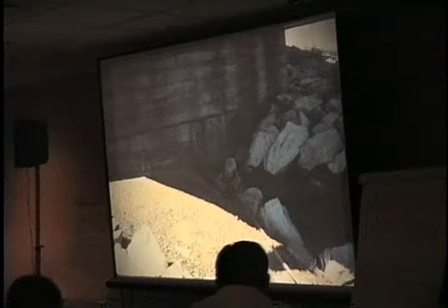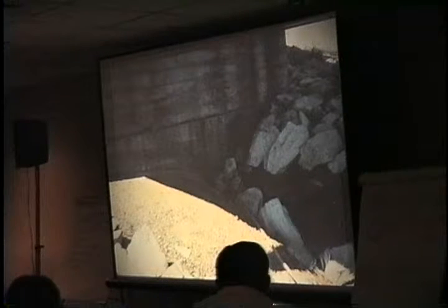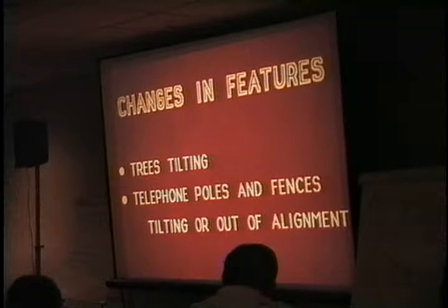They put riprap. Is that still a good thing right by the bridge abutment? I don't like it personally. I want to move that stuff off the approach. Changes in features: trees, tilting telephone poles, and fences out of alignment.